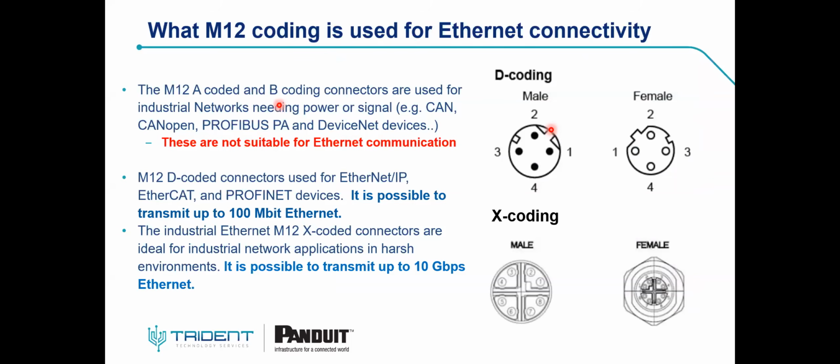Okay. The second introduction and addition in the TIA-1005 standard is the M12 form factor connector. The M12 connector is a circular connector, as I said before, with a 12 millimeter locking thread. It is used for industrial Ethernet communication in automation applications with a higher IP protection rating, up to IP68 or IP69.